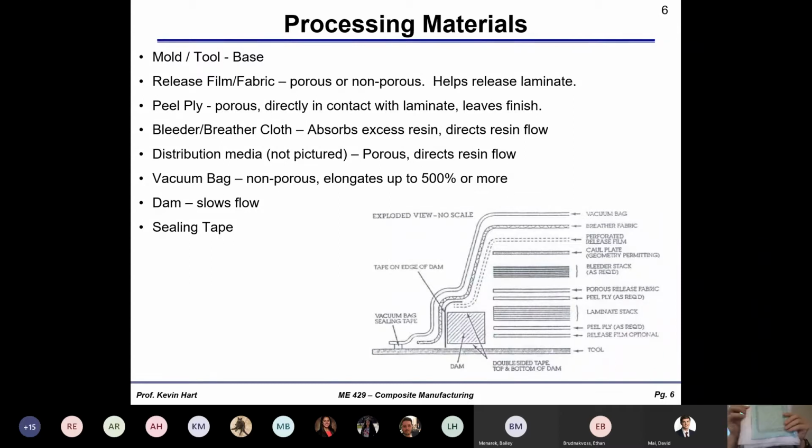When it came off of the thing, and then this white cloth here is kind of like a thick tissue over the top of that. So the entire assembly here would be this cloth, this nylon release that's porous, all over the top of what would be, oh god, that fell out. This is hard to do. What would be inside there, the composite material. Then there's an aluminum plate that goes over the top of this. You press it like a sandwich, and away you go.